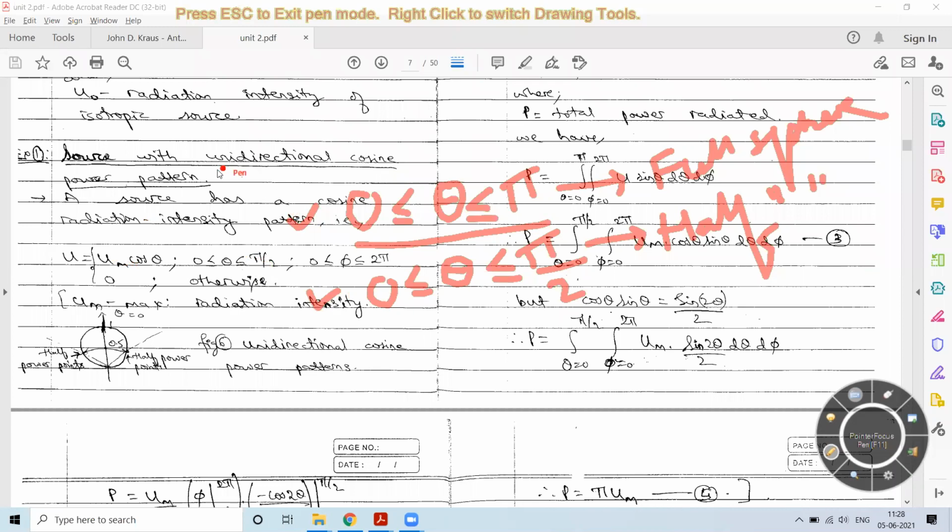Now, you come across this term which is termed as unidirectional antenna. You can have unidirectional or bidirectional antennas. So in these cases, what is the angle I need to consider? Now remember, if it is a unidirectional antenna, it is assumed that the antenna is radiating from, say, 0 degrees to 90 degrees. So if theta is equal to 0 to 90 degrees, and an antenna is placed over here, and I measure the radiation intensity, I'll be having values over here.